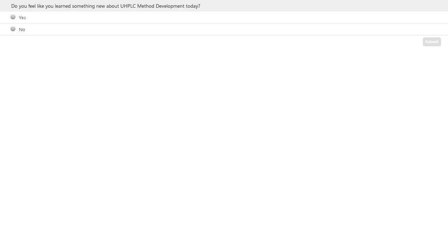Someone asks if you'd be able to explain again how to correct for porosity for translating gradient methods. Okay, no problem. It really depends on which brand you're working with as to how porous the column is, and it relates to the column volume. So the porosity is only going to change the volume of the column. What I mean by that is when we work out column volume, it's basically the volume of a cylinder, pi r squared h, times this porosity factor.